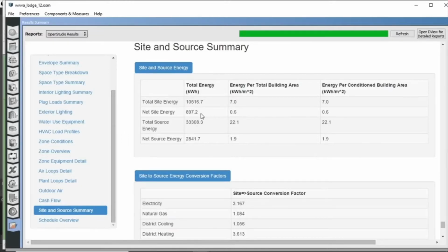Of course, we will not find exactness in values if we do the calculations. There are distribution and energy conversion losses. These losses add up from the PV array to the electrical wires to the DC-AC conversion, and finally the reactive losses going to the electrical grid. These factors are used to estimate approximately. They are good, in general, reliable estimates.